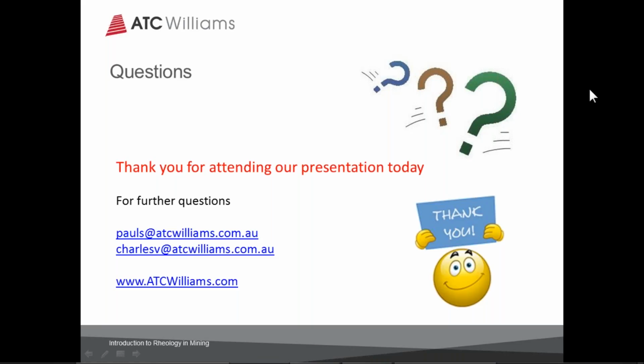Thank you, Paul. Question, so it's regarding the Metzner-Reed approach. In which case does it work really well, or can you apply it efficiently? Metzner-Reed will work very well if you don't have yield stress, or if you have a relatively low yield stress. Of course, it depends very much on the application and the materials being used. But once you start to get a significant yield stress, that's when the problems start to arise and the method becomes less accurate.